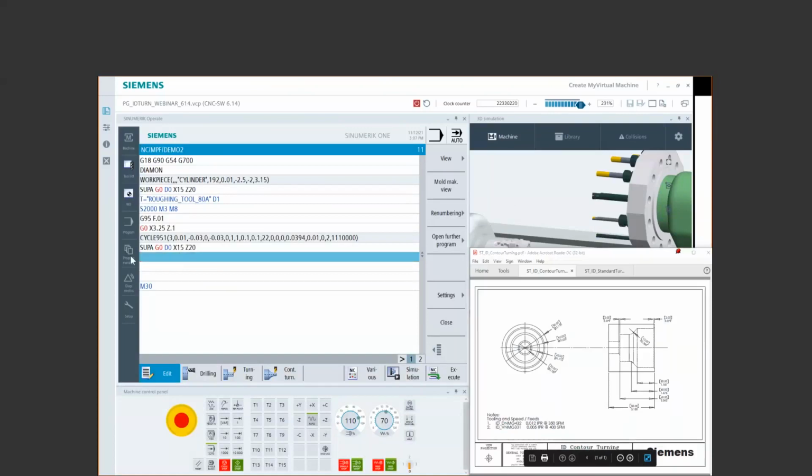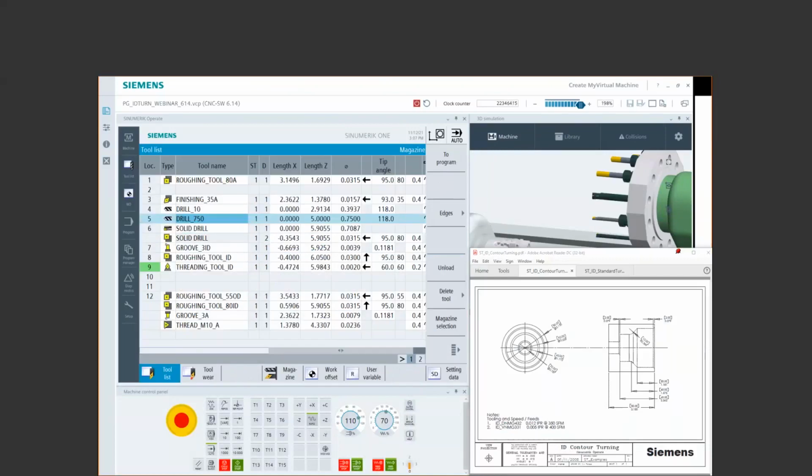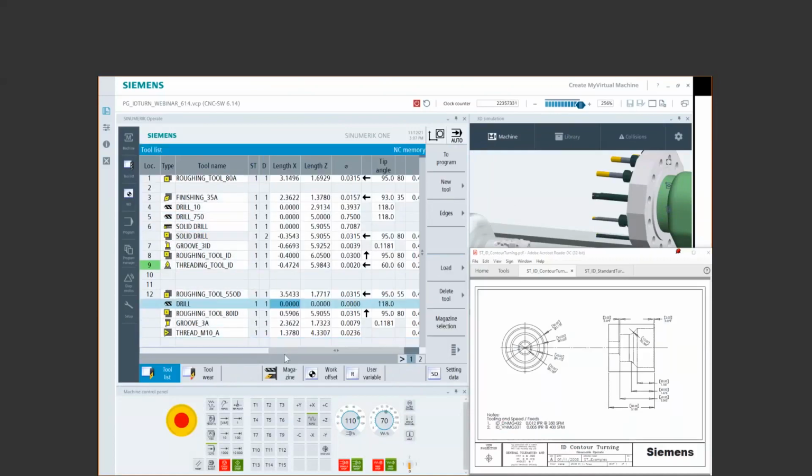Okay, so I'm in my safe position. Jump over to edit, expand back so I see my select tool and find my drill, right? So when I built the drill, I just created it simply like this, right? New tool, picked my drill, the way it's pointing to my chuck, gave it some name. Eventually I set the offsets later, gave it a diameter, and then on a regular drill, I would have an insert or a drill point angle. So I would define that.